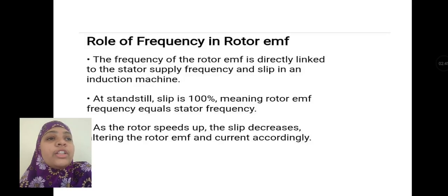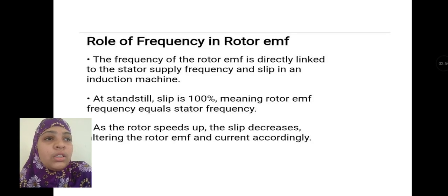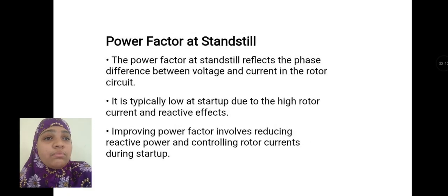The role of frequency in rotor EMF. The frequency of rotor EMF is directly linked to the stator supply frequency and slip in an induction machine. At standstill, slip is 100%, which means the rotor EMF frequency equals the stator frequency. As the rotor speeds up, the slip decreases, altering the rotor EMF and current accordingly.